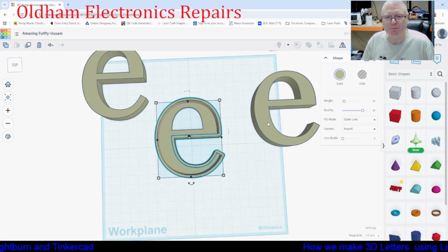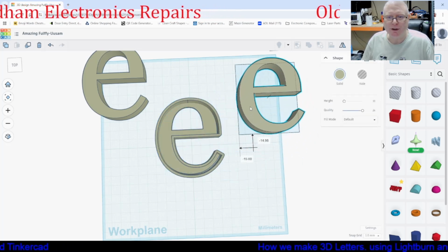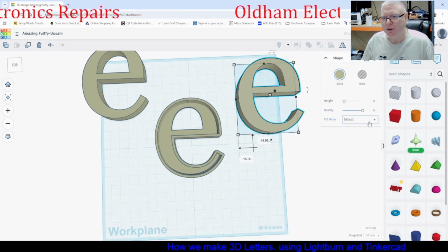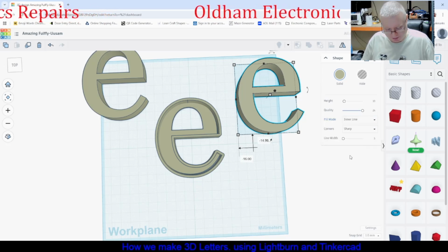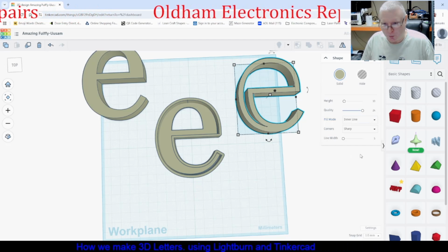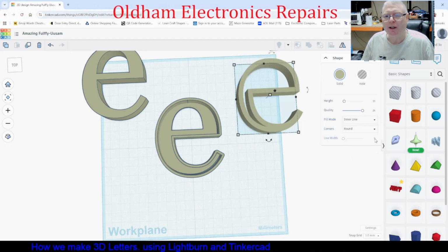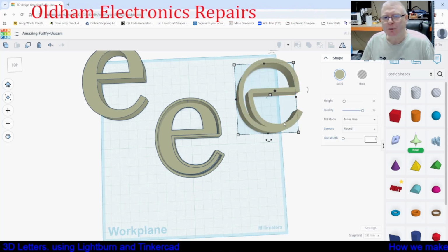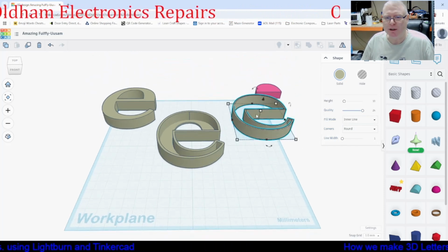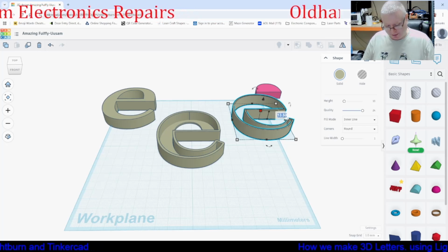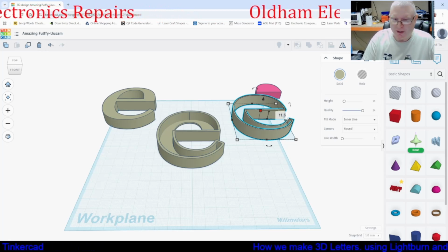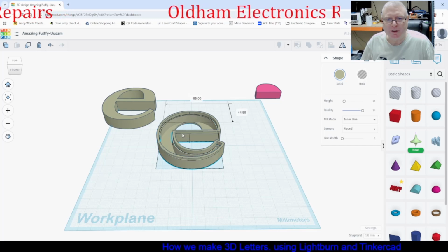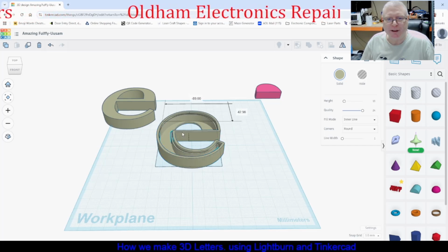We'll line it all up in a minute. Now this wants to go inside there to give us a lip. So we choose this one and we go inner line. And the inner line wants to be 1 millimeter round, 1 millimeter. But the height of this wants to be a little bit lower, so we're going to go 11.5. Now, so that will give us the lip inside.